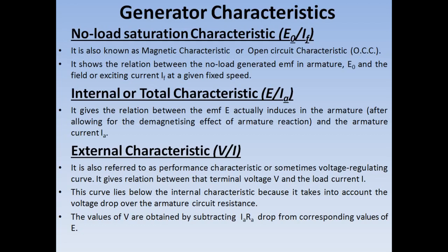The relation for no load generated EMF we are all quite familiar with. We have studied the derivation of that in our previous sessions. That is E0 is equal to PNZ by 60A. This no load saturation characteristics is just a magnetization characteristics, or I can say it is just a magnetization curve.